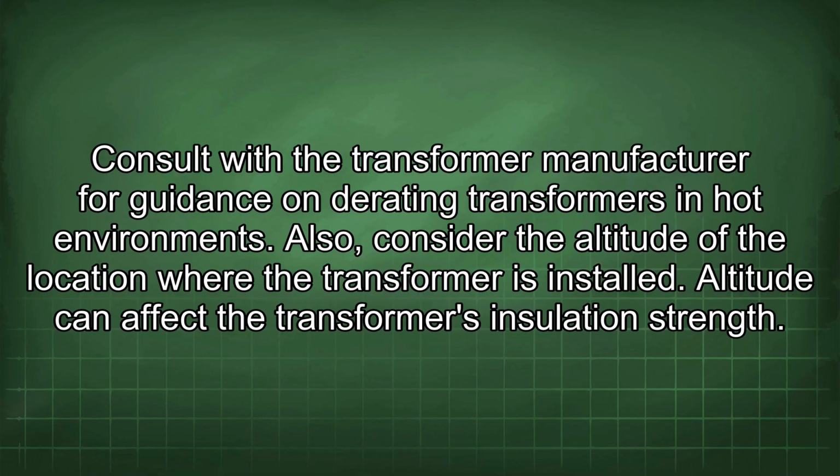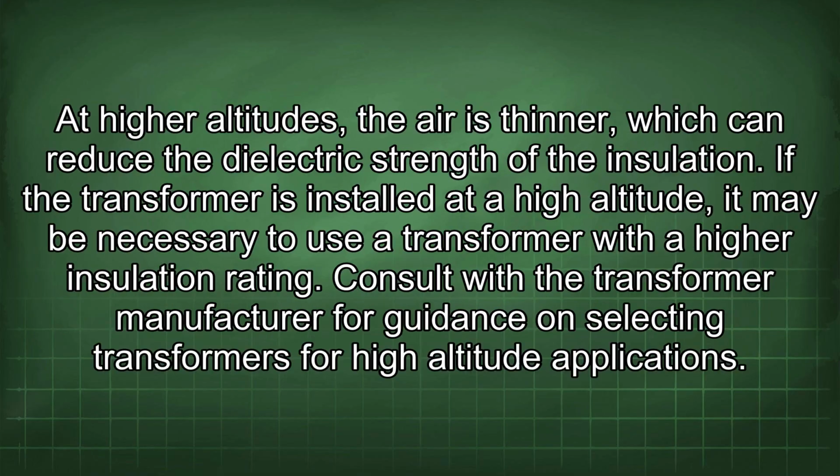Also, consider the altitude of the location where the transformer is installed. Altitude can affect the transformer's insulation strength. At higher altitudes, the air is thinner, which can reduce the dielectric strength of the insulation. If the transformer is installed at a high altitude, it may be necessary to use a transformer with a higher insulation rating. Consult with the transformer manufacturer for guidance on selecting transformers for high-altitude applications.